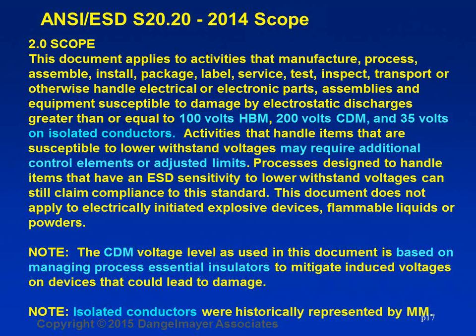No. Okay. Yeah, I think one of the things that Carl is stressing is garments may be used for many reasons in your facility, so you know who belongs in which area. There could be a team coding going on with the color of the garments, but if they're not being used for an ESD reason, then it doesn't matter if it's short sleeve, long sleeve, rolled up. They're there for some different reason. And there are difficulties with using them: you have to have very special garments and wash them a special way and replace them at certain intervals if you're going to use them as a grounding mechanism.